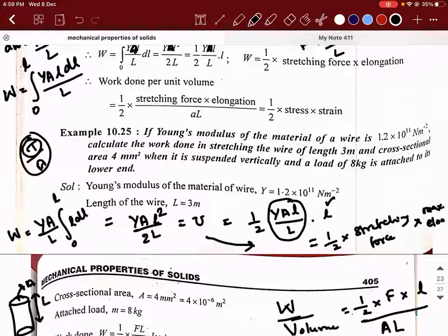But what is the stress strain graph telling us? You need to first cross the proportionality limit, then go to the elastic point, then to the yield point, then to the tensile strength, then comes the breaking stress. Right? So unless I know what kind of material it is, we can't comment anything. But to answer your question precisely, if tension is the one responsible for the string to break, yes, in that case you will take tension divided by the initial area, provided that the material is a brittle material, meaning it is immediately getting broken without undergoing any elastic properties.